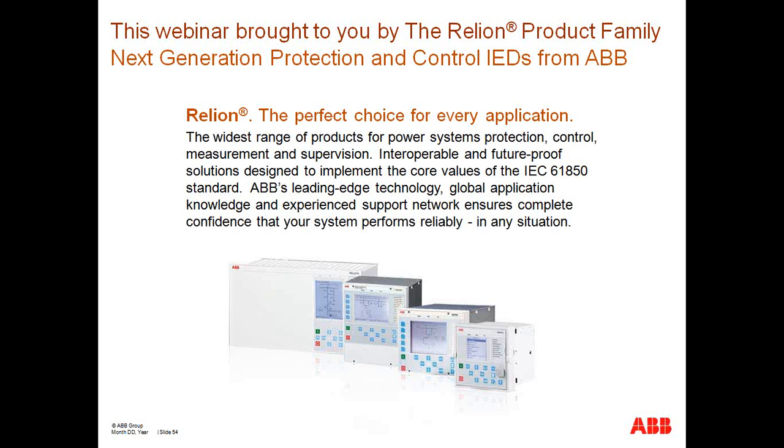However, I do see RTUs with the capability to model pieces of equipment that do not have electronic interfaces, such as breakers, transformers, load tap changers, becoming in higher demand if they're able to model that particular piece of equipment in 61850. So, for instance, if you have a conventional breaker, you can have an RTU or an I/O box that can have, from one side, the hard wiring to A and B contacts, close coil, trip coil, and status signals. Then on the other side, you could have an Ethernet interface that will, in turn, report the status of those signals, as well as having the capability of receiving GOOSE messages for trip signals or close signals. So that is an application where we see smaller RTUs becoming a part of this picture.